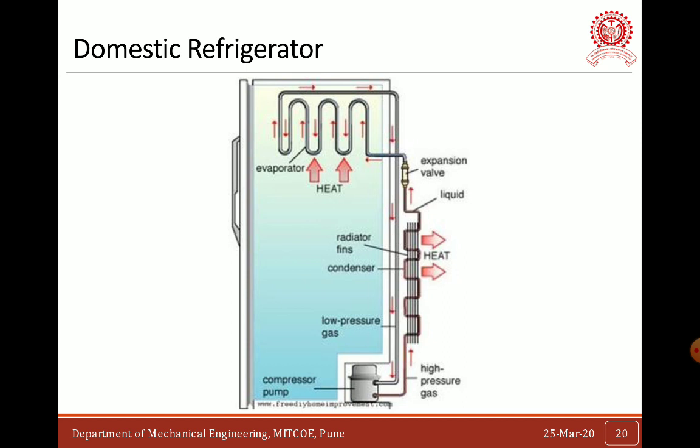And in new refrigerators such type of structure is not available, but if you touch your domestic refrigerator on the left or right side, you will find the condenser is there. You will feel it hotter than the atmospheric temperature. It is due to the condenser, it is not a malfunction. Okay, it should be there.